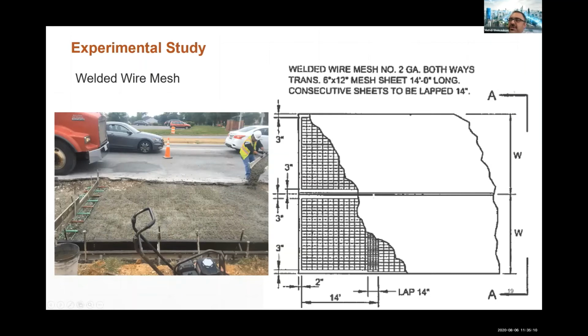And another thing, as I told you in the previous slides, the rebar, the wire mesh, basically are considered to be placed close to the surface, but in most of the cases, especially during construction, the concrete crews could walk on the reinforcement before the concrete is cured, so their placement is not as expected. And that can also change the performance.